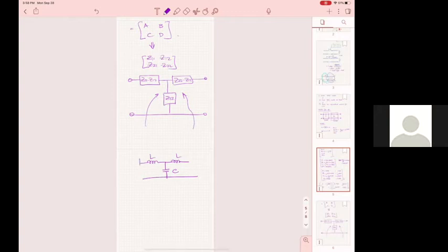And then I put a capacitance here. So if you were to avoid the ABCD and you remember that the transmission line has this symmetric L on its side and then C, and you could find those from the ABCD matrix, then practically your equivalent circuit is here. And this will be a different one, of course, C1. So you have 2 inductors, 2 capacitors.